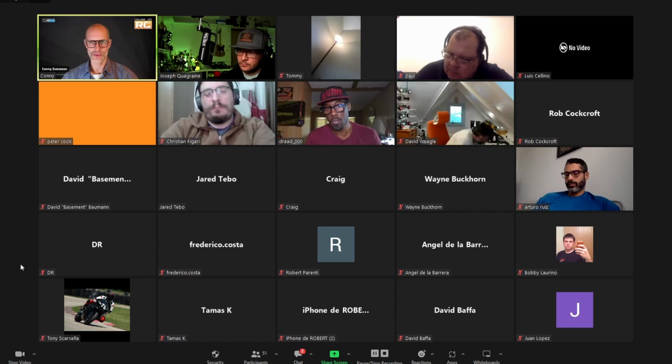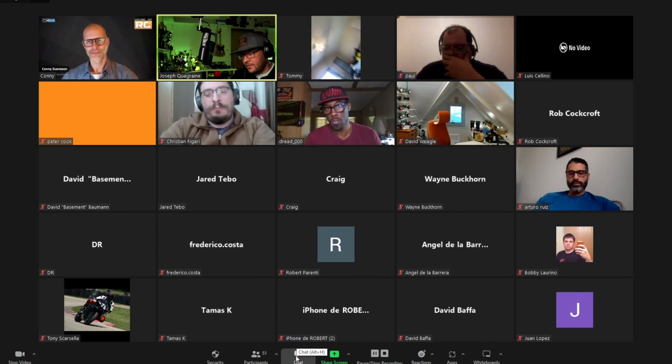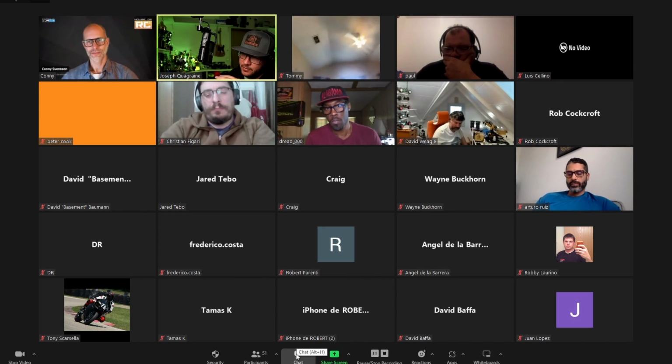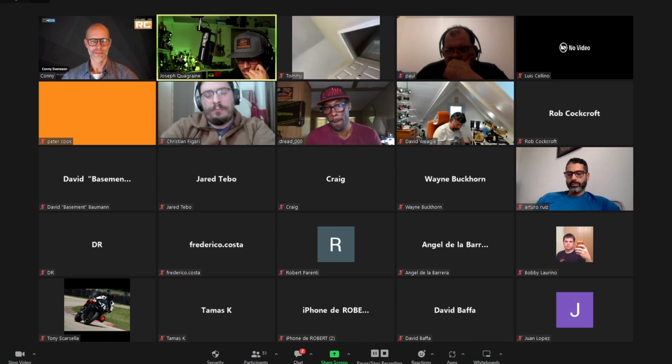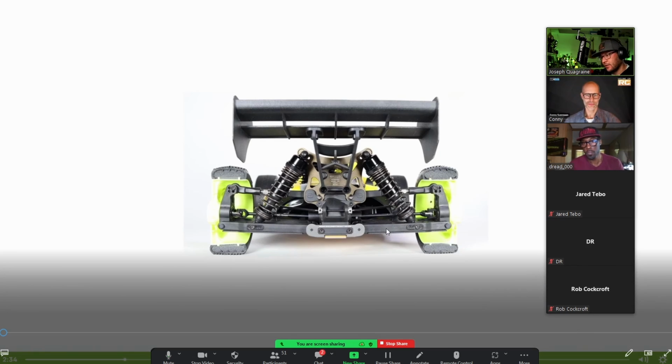Yeah, it did. How about you, Joseph? How do you approach that? We can go through this because someone asked something similar in the first meeting today. I'll show this picture. It will be easier to explain. This is how I think about the setup. We know that all these locations affect the roll center, yes, but the arm is a very powerful tuning aid because of the force that travels through it, not just because it changes the roll center.